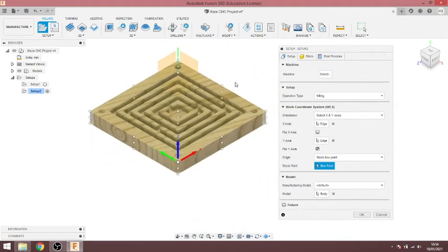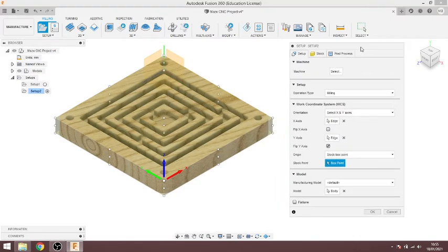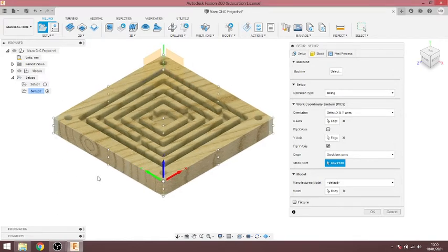So once you've got that set, now obviously if you put a piece of rough material in, you'd need to change the stock setup, but for pre-finished or pre-machined material, it's perfectly fine to have no additional stock. And you don't need to have that excess coming off the sides, because in the operations I'll show you in a future video, you'll see that you can make assumptions of the stock size you put in.